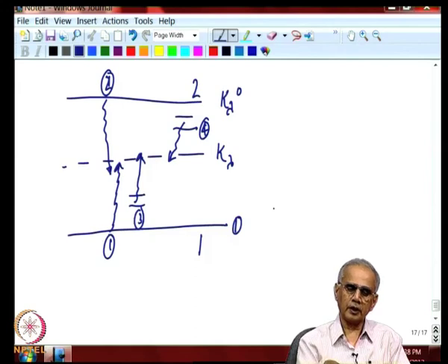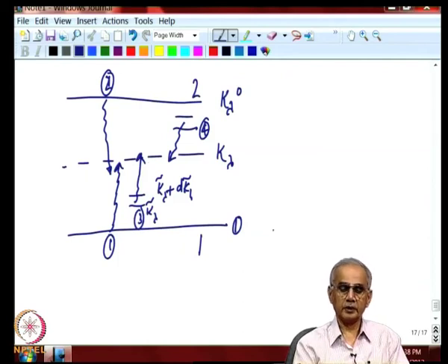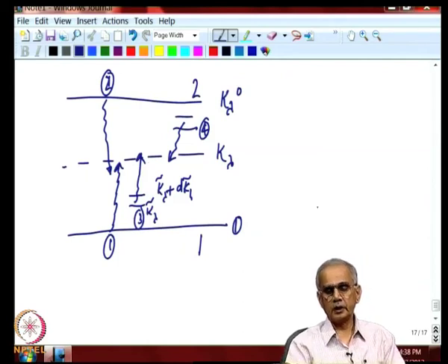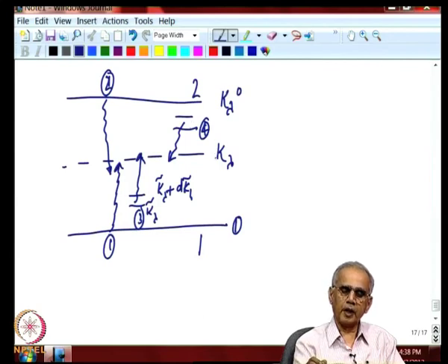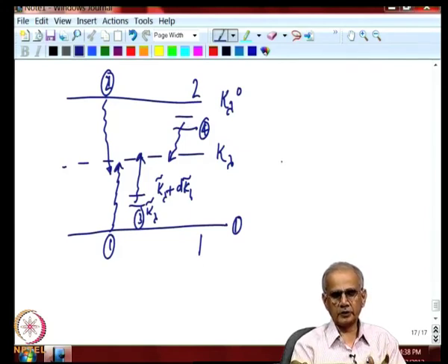And the two other terms are radiation emitted by all layers from kappa lambda tilde to kappa lambda tilde plus d kappa lambda tilde, this layer, and integrate all emissions from surface to kappa lambda to get the third term. And the fourth term is radiation emitted downwards by all gas layers lying above kappa lambda, and so they travel distance kappa lambda minus kappa lambda tilde, which is built into the exponential integral function.